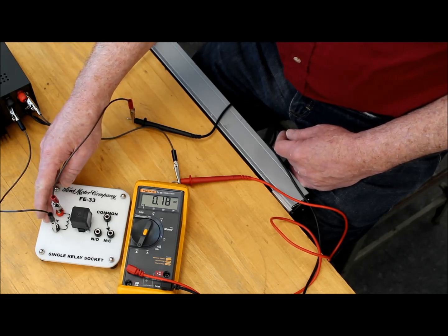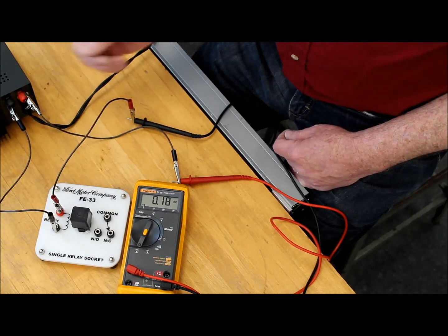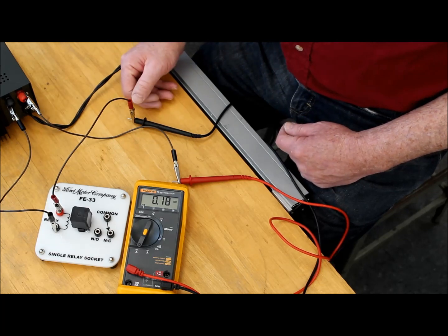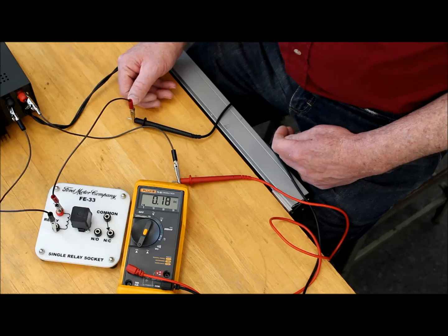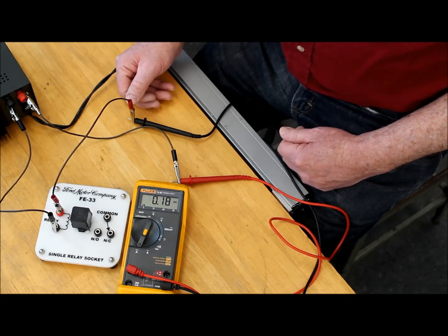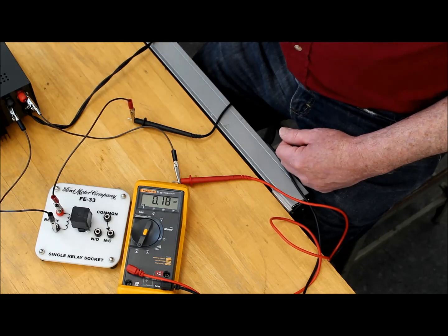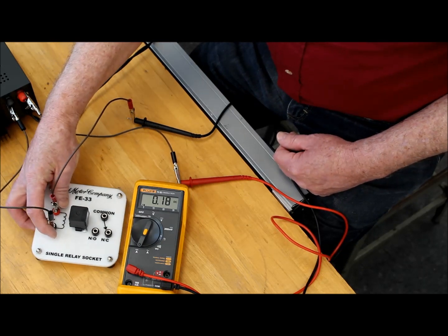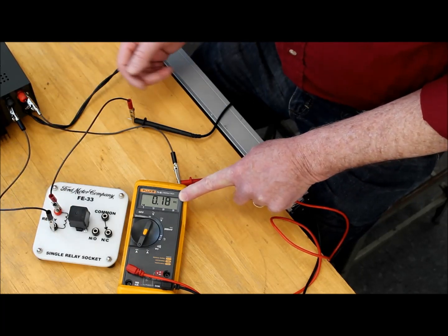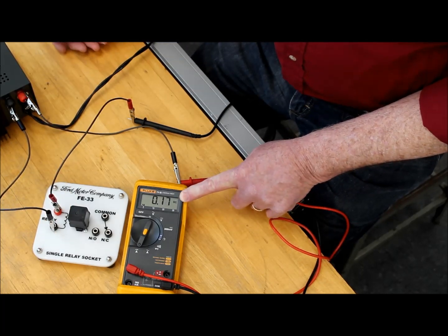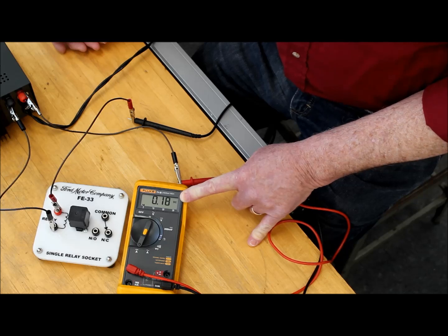You push a power window switch, you're telling the computer, I want the window to go down. It needs to energize that window motor, but it can't handle 3.5, 4 amps of current flowing through it. So what's going to happen instead is the computer is going to energize the relay coil, and as you saw, that's not even 0.2 amps, so a fairly small amount of current.